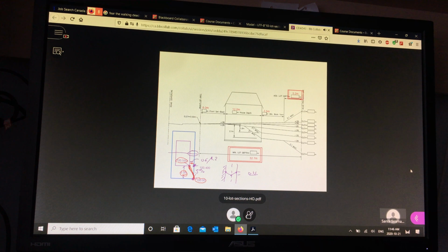It's going to be 6 point something, which means that's also happening on the other side. So the entire front yard is steeper than 5%, and that's not allowed. The maximum slope for a usable space is 5%. So if I use 5% to do my work, there's no way that the architect can achieve a maximum of 5% inside the lot.